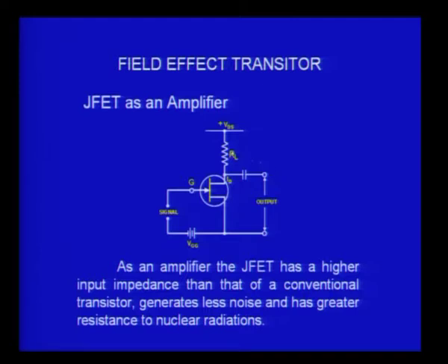So the basic junction field effect transistor can in principle be used to amplify small signals in the order of a few millivolts, because the field produced by millivolts is very large, it will control large current flowing between the drain and source, and therefore it will produce a large voltage variation after the capacitor at the output. That is the basic principle of the amplifier.